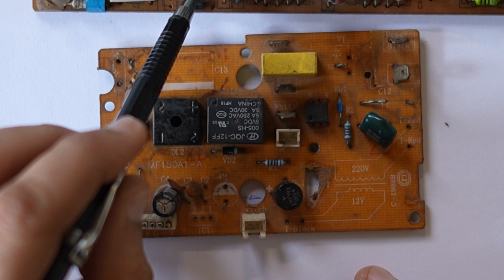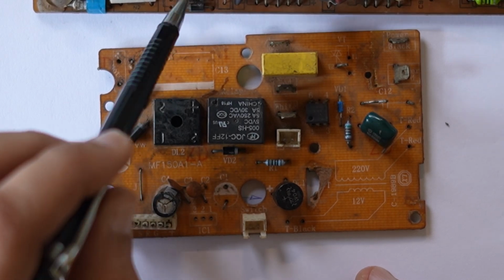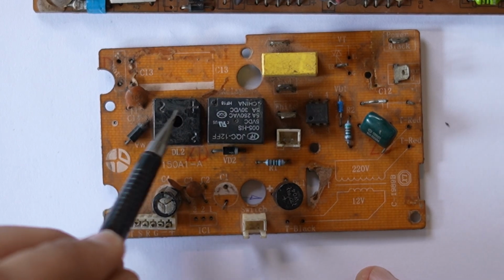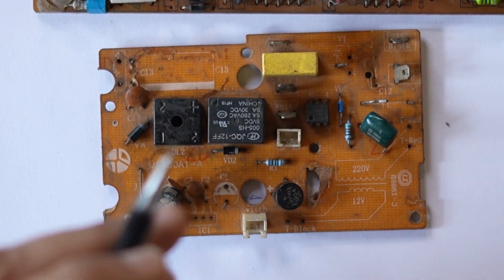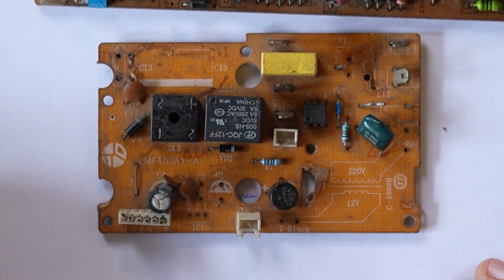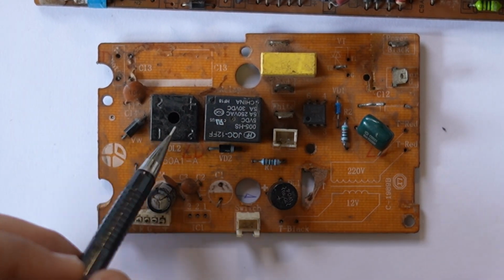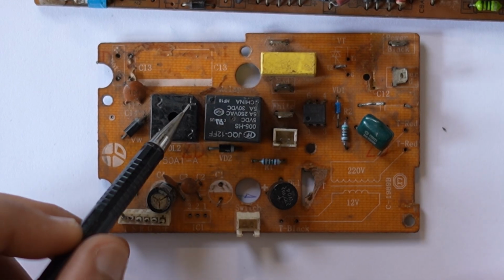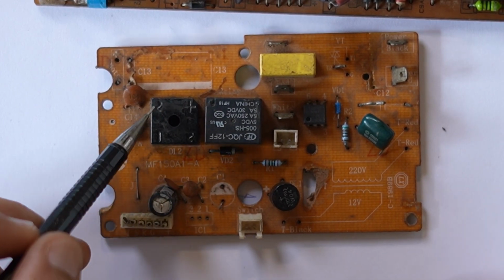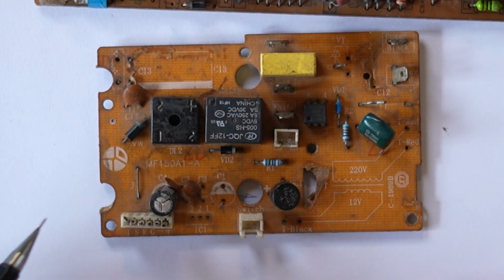So instead of installing 4 separate components and soldering 8 pins, you just install this one block and you have 4 pins, and it makes for a neater, easier production process and so on. And you'll notice that it's marked with plus and minus. So that's the output, the positive side and the negative side. And these sine wave symbols here, where you have the sine wave or the AC input.